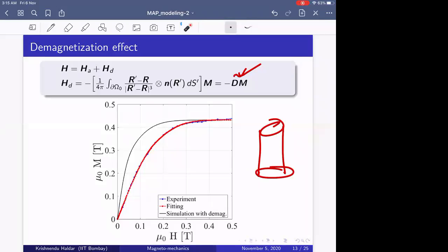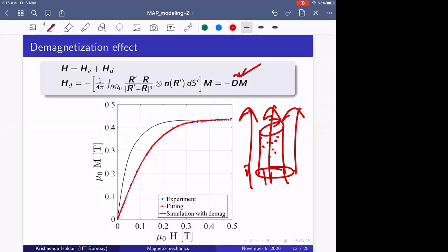This stress is like, whenever you are applying some magnetic field, if this is the material and this is the ambience of some magnetic field. So magnetostress, you can think about it as, for this material system, as we have magnetic fields, they start interacting with each other. So naturally the body will get stress inside whenever you switch on your magnetic field. They are inherently generating a stress condition inside the body, and this magnetostress or Maxwell stress will take care of that stressing effect.